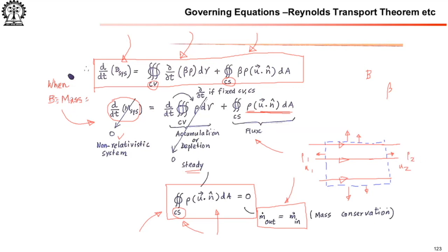Now, we said that density does not change in incompressible flow fields, but because this is a course in introductory aerodynamics, we are not restricted to incompressible flow per se. Your density can change. For example, if there is a shock wave sitting somewhere in between, you can have a situation like this. If you have heat addition, you can have something like this. So density is changing, velocity is changing.